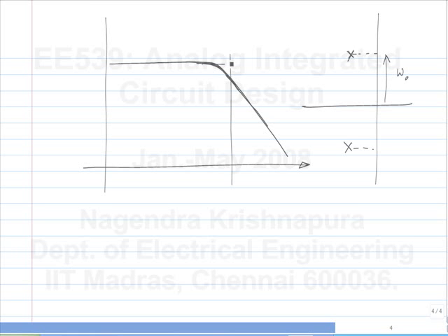Of course, there is no guarantee that it will do that, meaning you can get a flat one because, for instance, you could by some weird circuit make it ring here. With L's and C's you could do that. Then probably you cannot do this. What will happen is you will get something like this. That is not useful, but in this case it turns out that the tendency to ring you introduce lies just beyond the bandwidth of the circuit without ringing. Okay, so it becomes flatter.